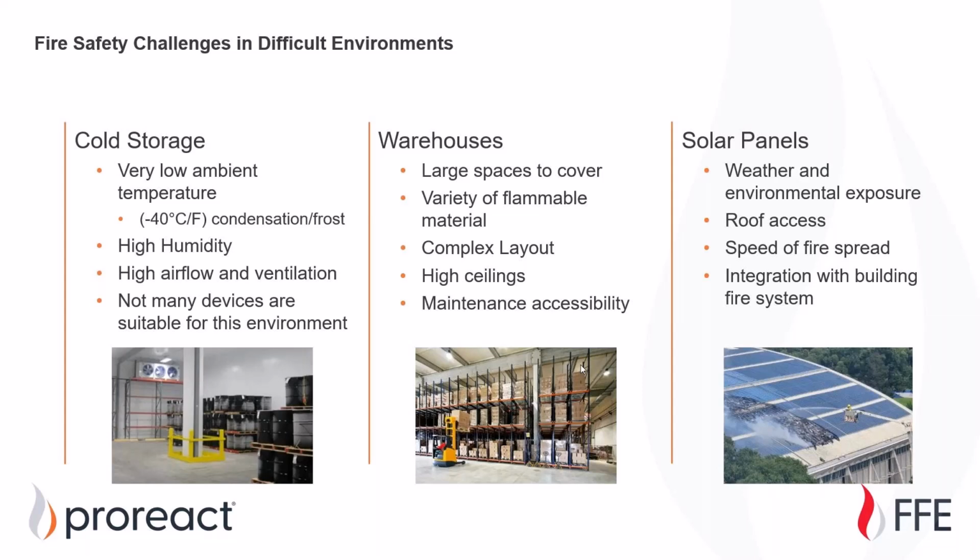And then for solar panels, obviously these are outdoors. Parts of the cable can get direct sunlight. You can try to have them shielded from direct sunlight. Also, another challenge is that the solar panels themselves, the surface temperatures can get so hot they can sometimes get 30 to 50 degrees hotter than whatever the ambient temperature of the air is, based on all that solar energy being absorbed. So depending on what your proximity is, that the cable is to your PV cells, could depend what that ambient temperature is and greatly affect your detection times.